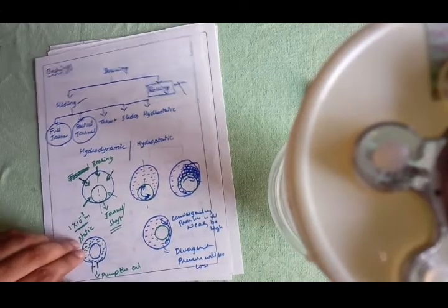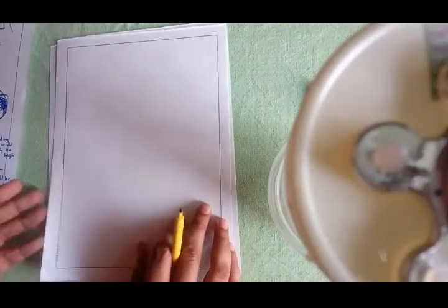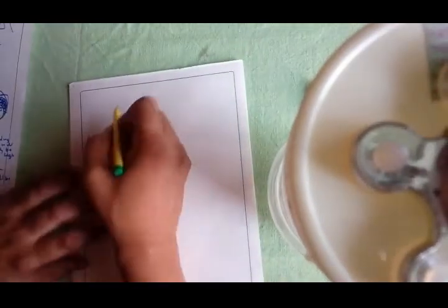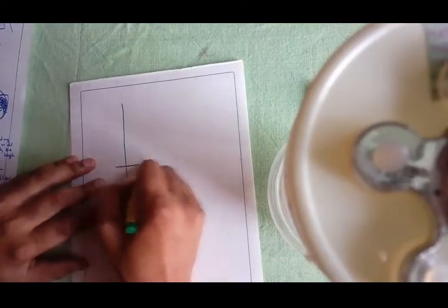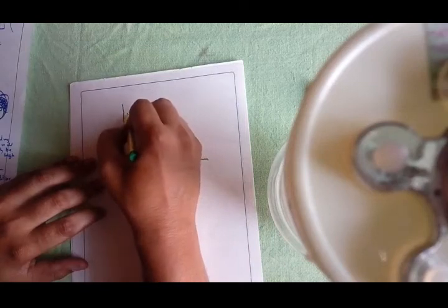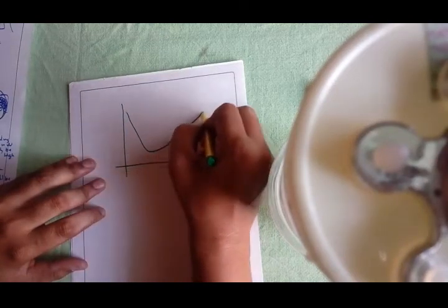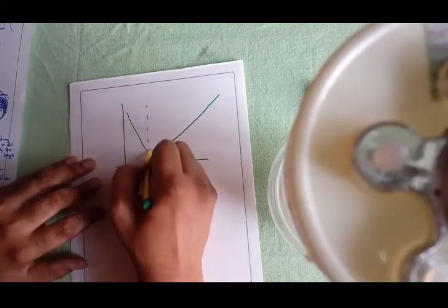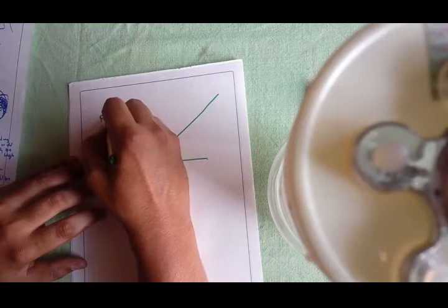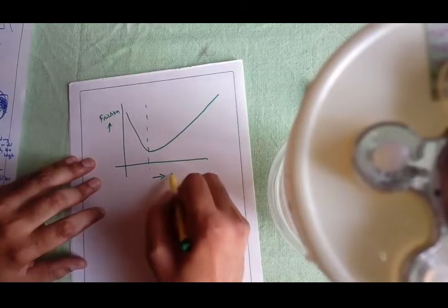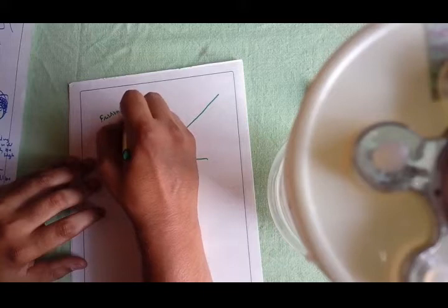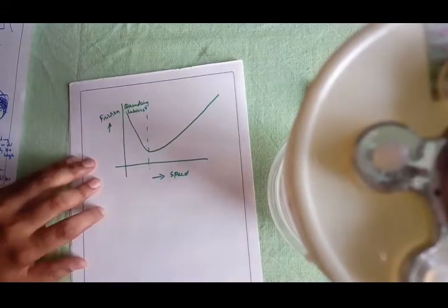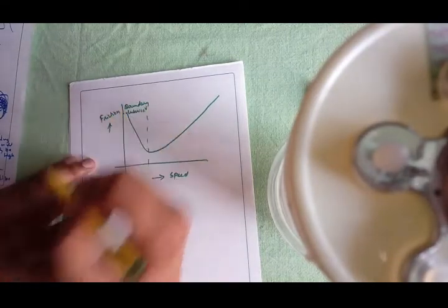Now how are you going to achieve this? First, it is going to take some time to build this thick oil film. See, initially there is boundary lubrication, and later as the speed of the journal is increased, we can achieve thick film lubrication. The friction will be reduced with the increase in speed. Here initially you are going to see the boundary lubrication, and initially the friction will be very high.